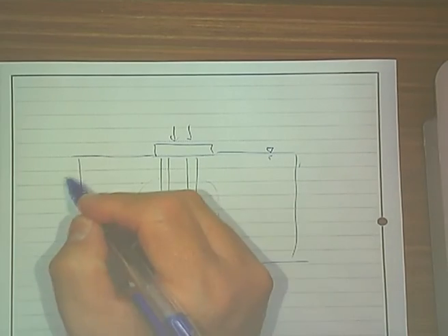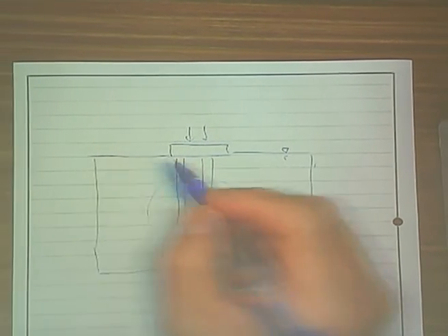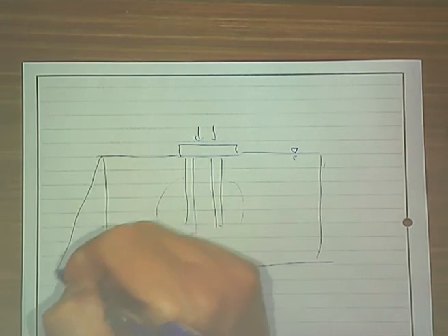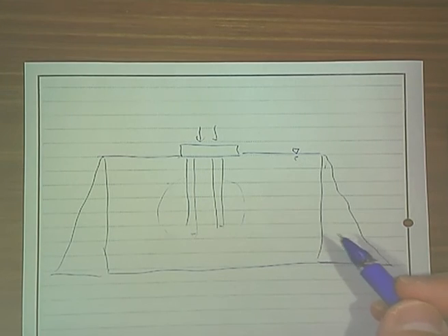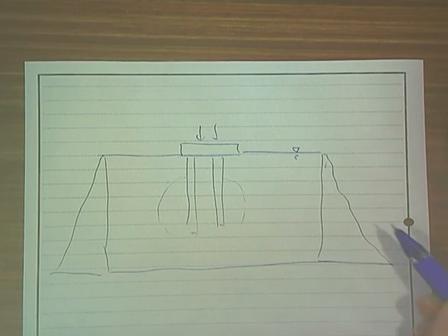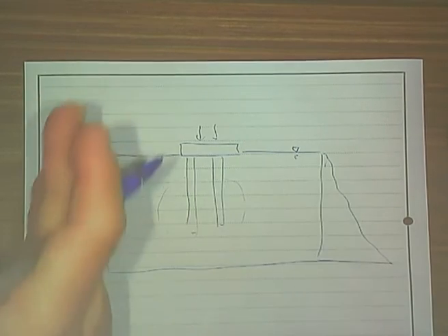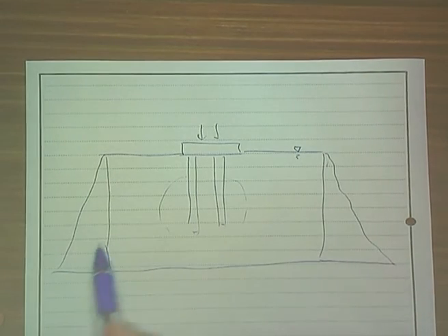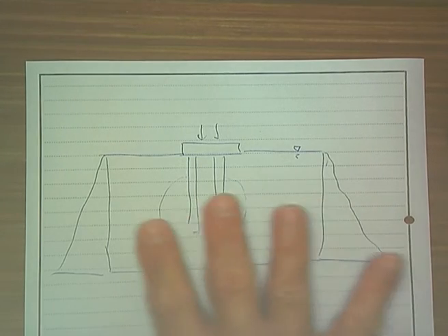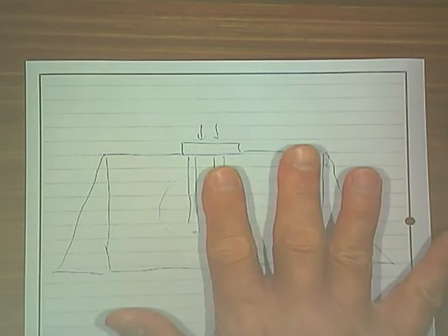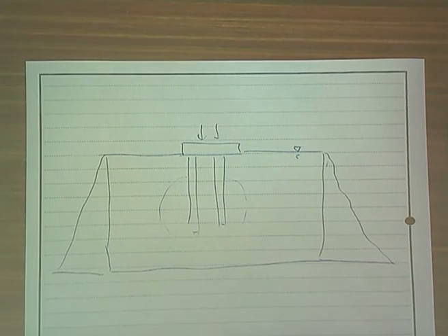Then you can say that far enough away from the pile, the water pressure will be hydrostatic. So this is how you would specify your water pressure, hydrostatic pore water pressure. So this means that at all times, the water pressure on the left and the right boundary are hydrostatic. Therefore, when you do a drained analysis, all the pore pressure inside here will automatically be hydrostatic.